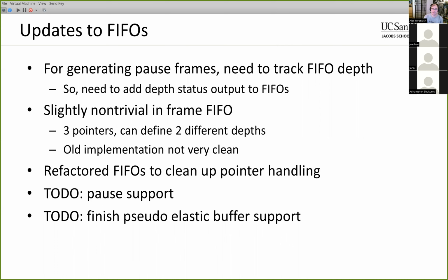Now, in terms of the FIFOs, there's a couple of modifications that I've been working on here. The first one is for generating pause frames. We need to be able to track the FIFO depth, so we need to add depth status outputs to the FIFOs, because that would make a lot of sense. There's probably a few other use cases where that would be handy.